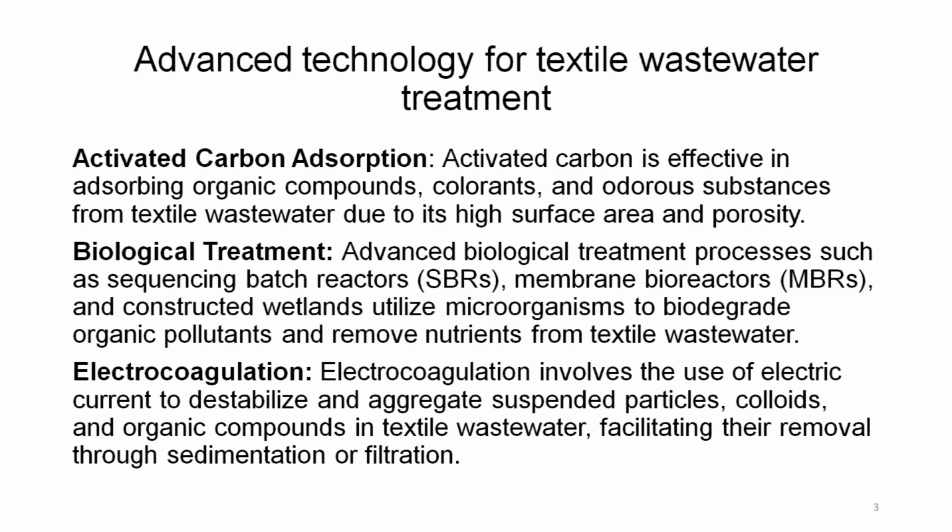Activated carbon adsorption. We have learned this, but we will see this in more detail. How does it work? What is the functionality? Activated carbon is effective in adsorbing organic compounds, colorants and odorous substances from textile wastewater due to its high surface area and porosity. The porous part in the activated carbon helps in the adsorption.